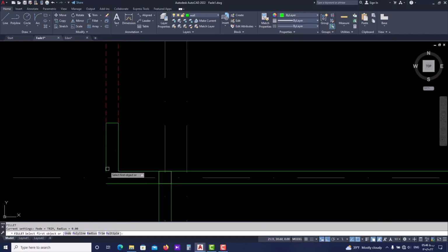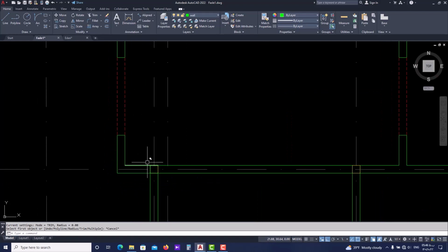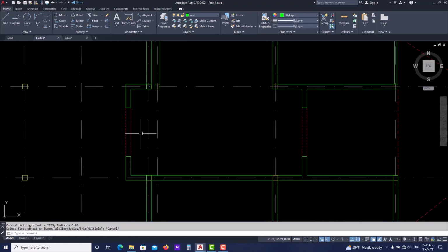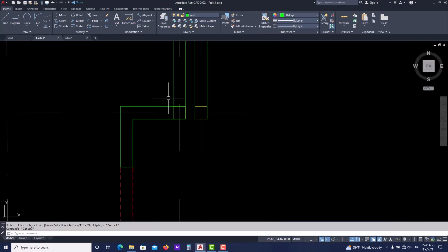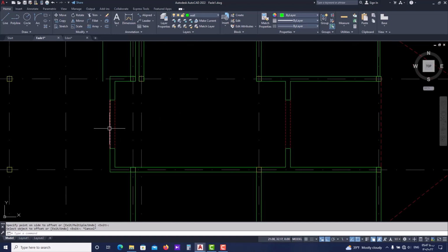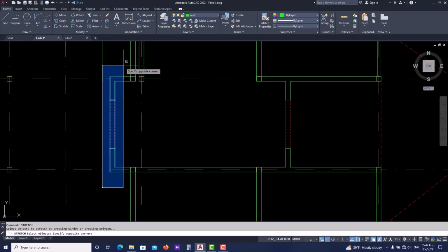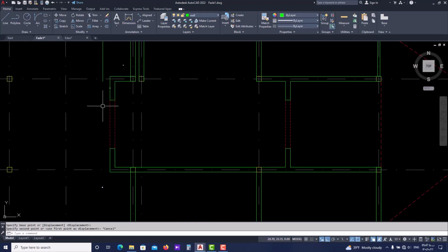So basically you just need to know when to use which technique, and just like this you can see how much faster you're working. So we had 1.15 meters. We can put an offset here for 1.15 meters. Then we can stretch this part, SCR, and select our items, and after that we can just select it and stretch it. Oh, we didn't select this correctly.